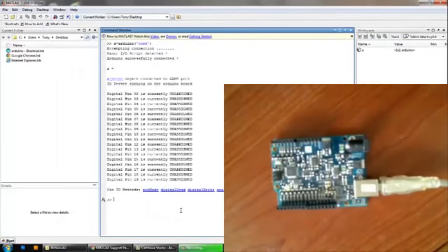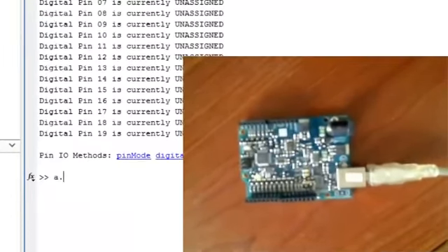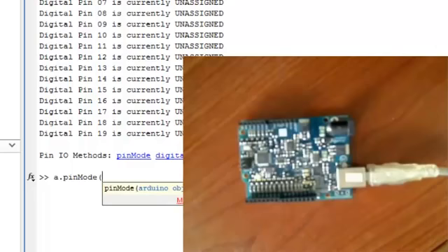Okay, let's just quickly show that we do indeed communicate between Matlab and the Arduino board. I'm going to assign a couple pins. Let's see. So I got a.pinMode, and let's do 13 again, because pin 13 controls that LED. We can see it in action real quick. So we'll do 13, and this will be the output.